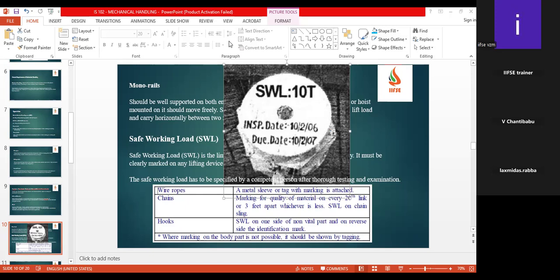A goods lift will definitely have an interlock so nobody will travel, but even those interlocks we have to cross-check, especially wherever manual operations or a person is involved. We should have a dedicated list, or identify them with a different color safety helmet, or any other means of identifying them immediately, like we do for first aiders. They have a green helmet, or a red helmet for the ERT team.